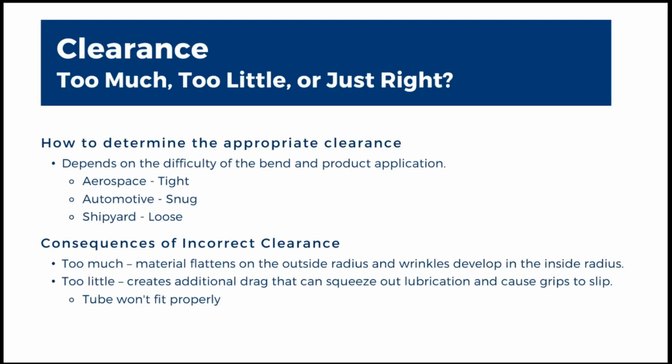Another key note about material specifications. The range of variation of the dimensions of the tube allowed by the spec can exceed the automotive and aerospace bending clearances we discussed above by 2 to 3-fold. Understanding the sizing of your material or having a mandrel size to your specific material can save you a lot of unexpected issues, scrap, and cost from one lot of material to the next. When you are using material with weld seams, it adds another layer of issue to discuss outside this presentation.